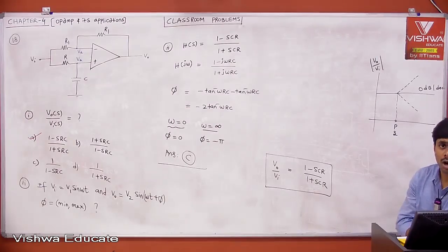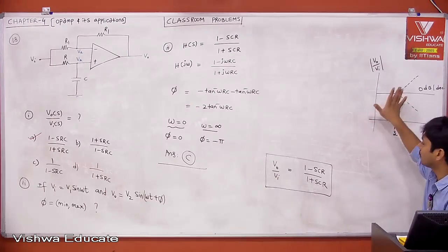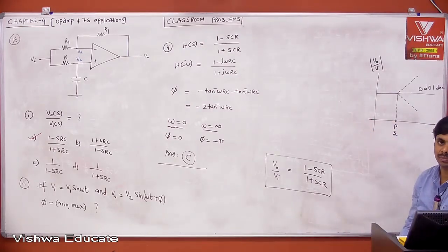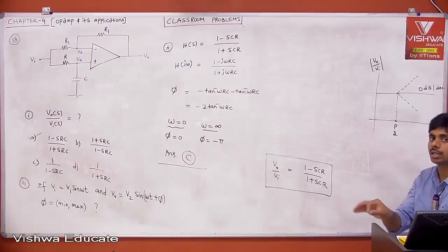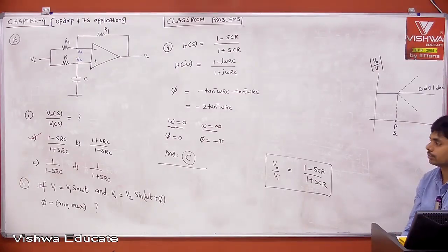Try to solve on your own if this is over. Problem number 14. But theoretically, if you ask me what this is, this is an all pass filter but providing some delay. Then a time domain delay is represented in the frequency domain as phase shift. But the phase shift should change linearly with respect to frequency. That implies constant time delay in the time domain.